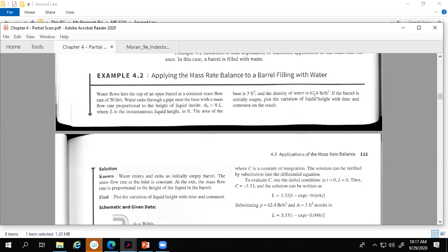But anyway, it's good to know a cubic foot of water is about 62 pounds. And it changes a little bit with temperature. You heat that water up, that water's going to be a little lighter. The molecules spread out a little bit. So if that was 200-degree water, that might be, I don't know, 59 or 60, something like that. But it's someplace around 60, 62 pounds per cubic foot. Good number to know.